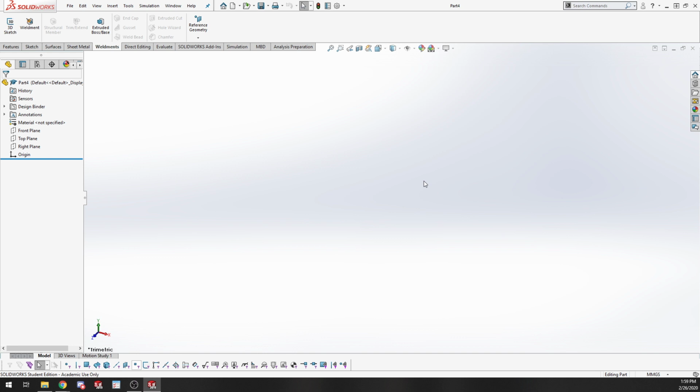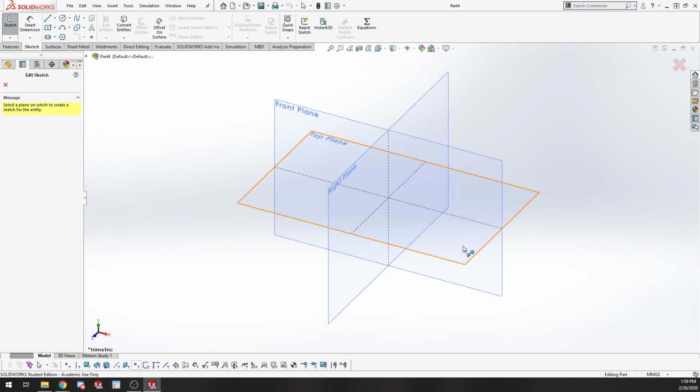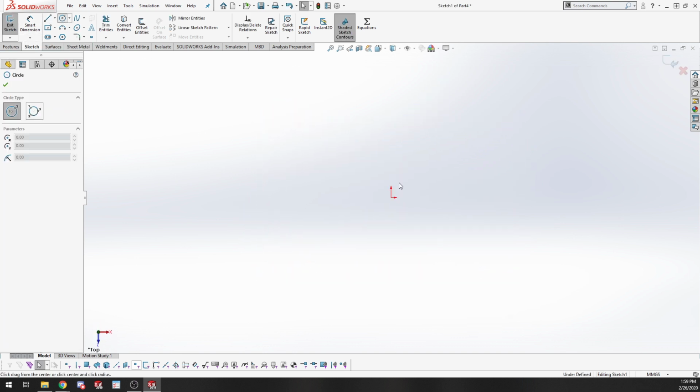And with surfacing, the trade-off that you get is basically, do I do solid modeled parts with extruded bosses, bases, revolves, and let SolidWorks do some of the control for the surfaces that are needed to create that, or do I go in and have finite control over every single surface within my part? Just to illustrate that, we'll make a super simple example. This is a common example that they use a bunch in all these surfacing examples.